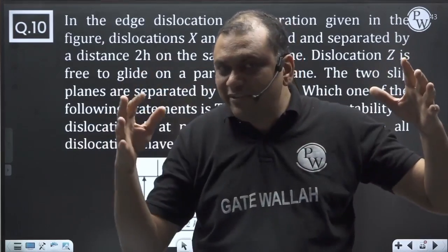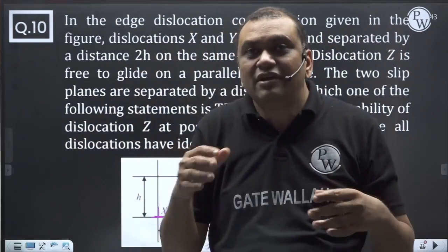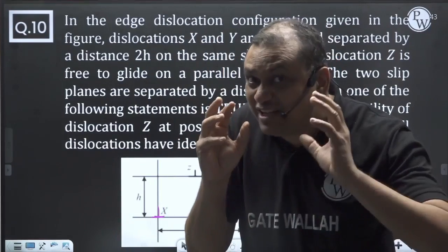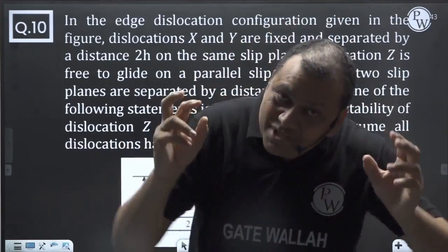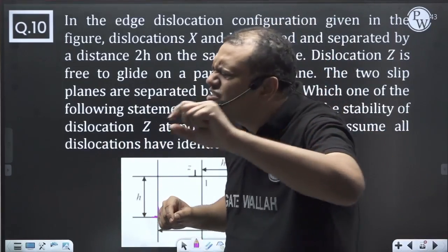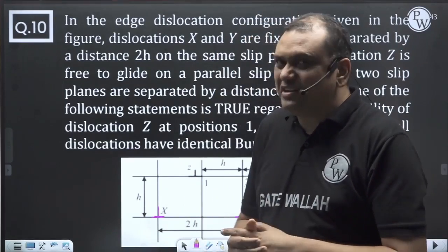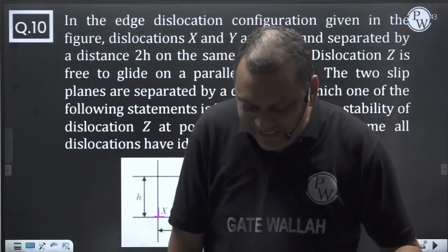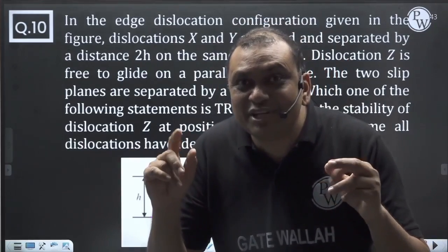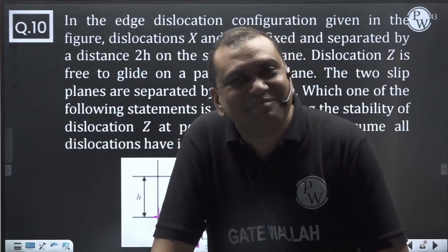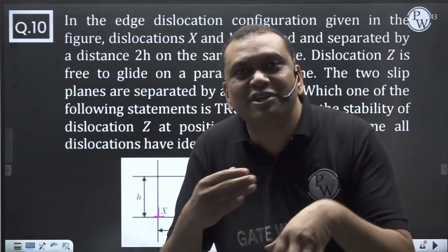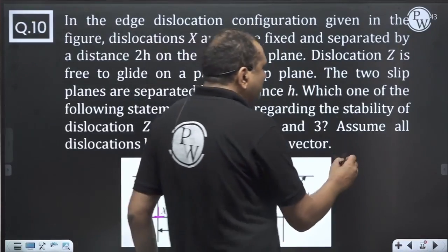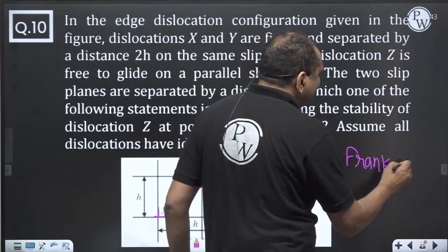And the stress at which dislocation begins to move in the material is called critically resolved shear stress. Now hear carefully, the moment dislocation begins to move in the material, the number of dislocations multiplies. How exactly does the number of dislocations multiply? There is something called the Frank-Read source.